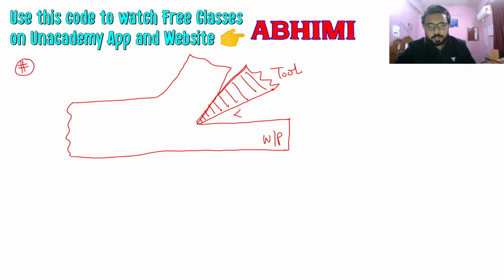Your tool is moving in this direction, and this right here is the shear plane. The shear plane and the cutting velocity will make some angle, and that angle will be the shear angle. So that shear angle will be the angle between the shear plane and the cutting velocity.